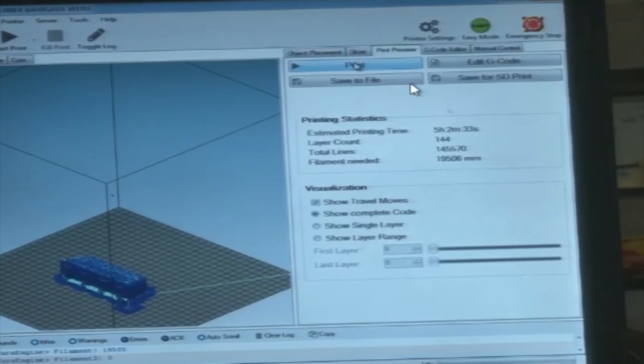Now there is another way. If we go to the print button and click print, all these manual controls that we set manually will be enabled automatically, because the bed has to be heated, the nozzle has to be heated, and the fan has to be kept on. All the settings we made before are activated by just clicking this button. So this is the automated mode.